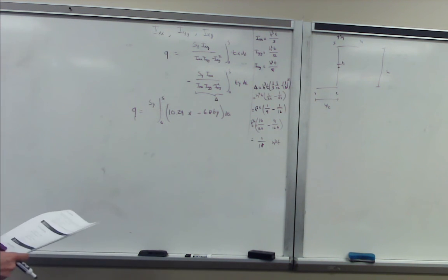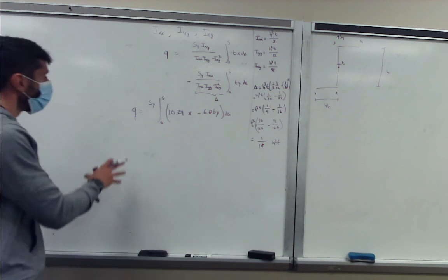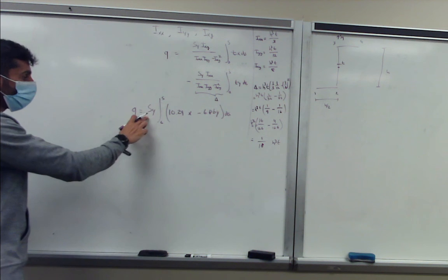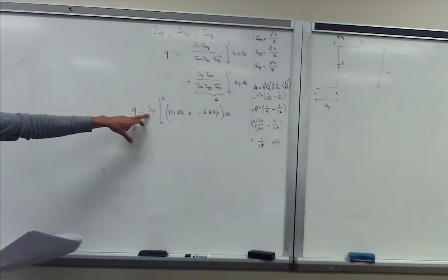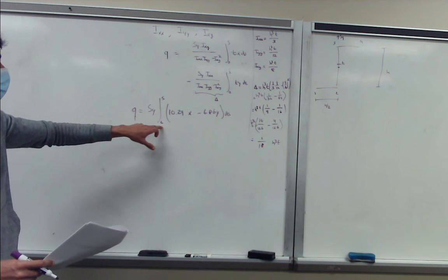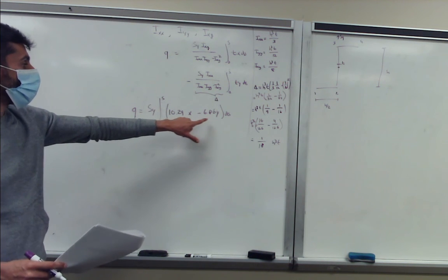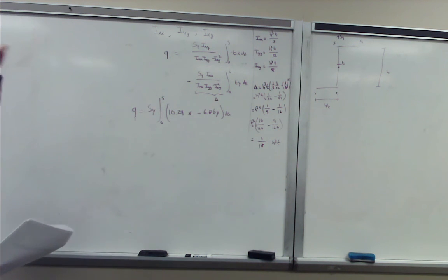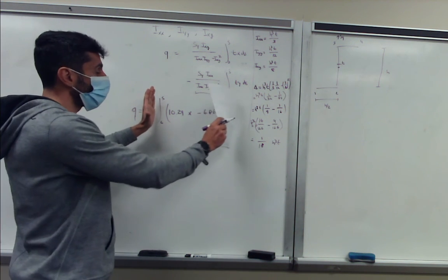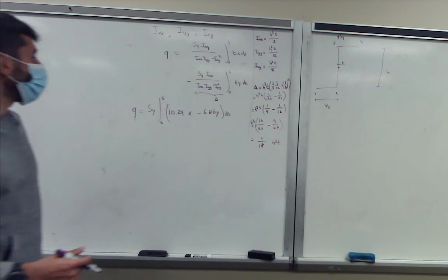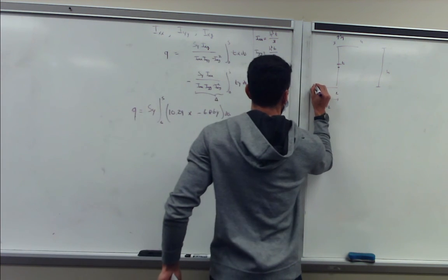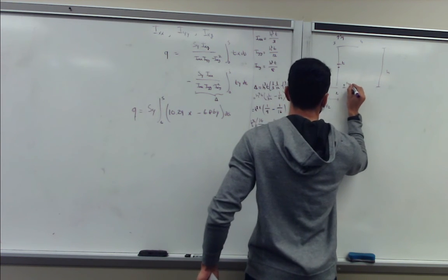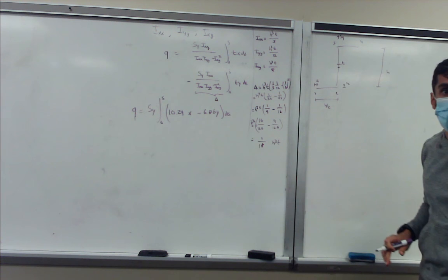But important is that we get the following equation out of it. So we know that our shear flow is dependent on our shear force, the location of our pad S, and the coordinate system x and y. So now the trickiest part in shear flows is basically getting this integral part correct. So what does this integral from 0 to s mean? You start off with a certain location. So this is your S1, this is your S2, and you go around your cross section.